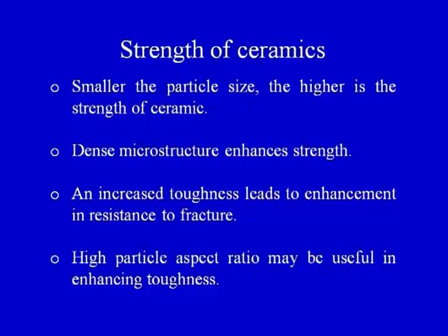So basically there we will address how the size of the particle would affect the mechanical properties of the ceramic product. When we make the ceramic from powders, the properties of the powder would affect the mechanical properties of the ceramic product. Dense microstructure enhances strength. Yes, if the porosity is less, we will get better mechanical properties.